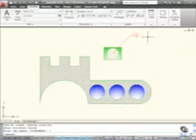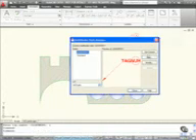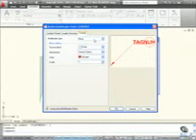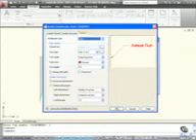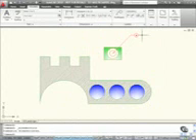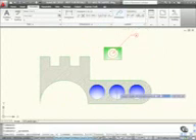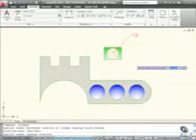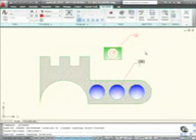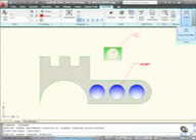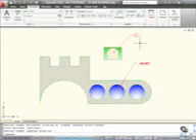If I go back to the style now though, and modify it, and change the content tab to mtext, and then OK that, and then close, the bubble remains. It's not like dimension styles, for example, where they update. So if I now do a leader and go from this center here and come up here like that, it now prompts me for some text by going into the multi-line text command. See the text editor comes up on the ribbon there? So I'm now going to put in there widget. So that's a widget there. So I'll just close the text editor, and there's my multi-line text instead of my tag number bubble.